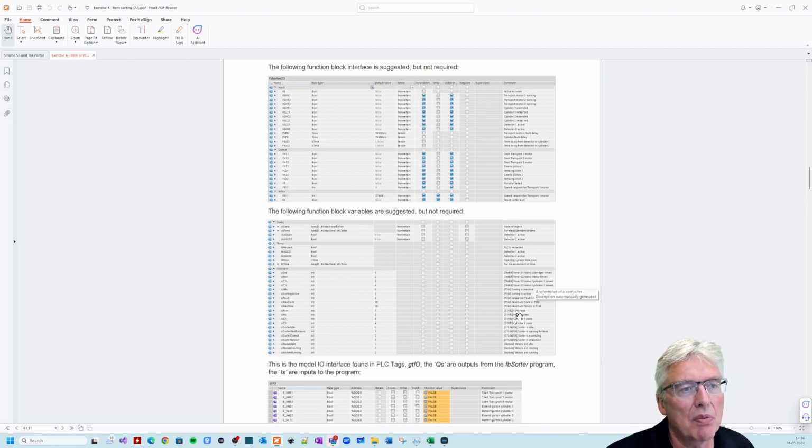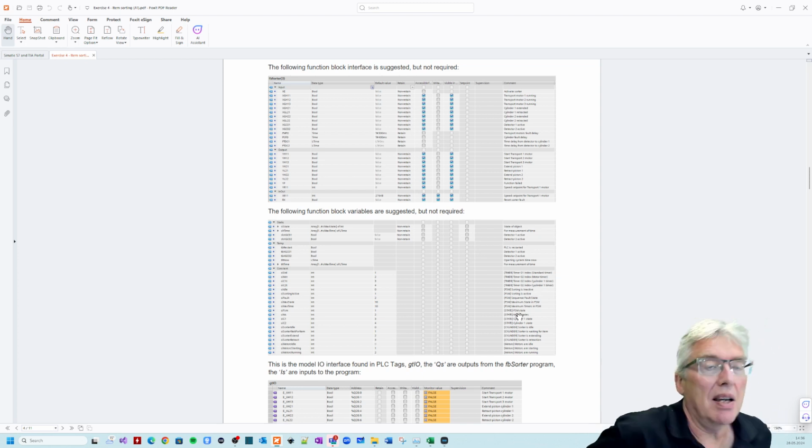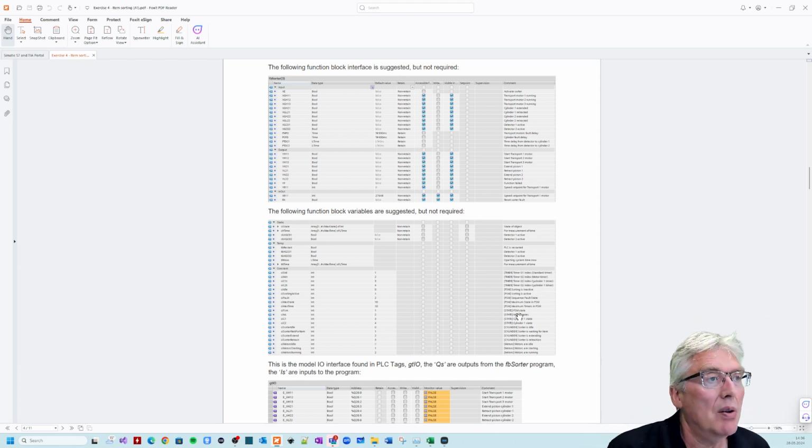If we are writing just one program, we need maybe a state machine for the motors, a state machine for cylinder 1, and a state machine for cylinder 2, injector 1, 2. They are identical, so maybe we should make a function block and inherit that too. And also maybe we should make a function block for each of our actuators that's checking the feedback. Is the motor starting and giving us an error?